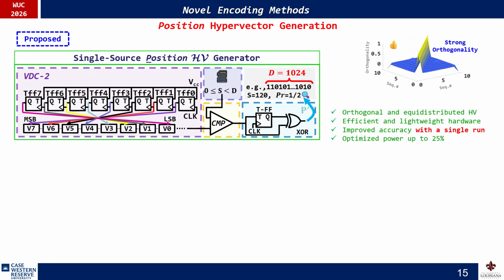For this one, at the output of the comparator as a regular setting, we propose using T flip-flops, where the shifted and the regular versions are XORed, which guarantees that we can have many different types of orthogonal vectors from the output of the comparator, having 0.5 probabilities as the requirement of orthogonality, but each with high quality orthogonality. With this, we just use a single source and multiple different versions of the vectors for our n different symbols.